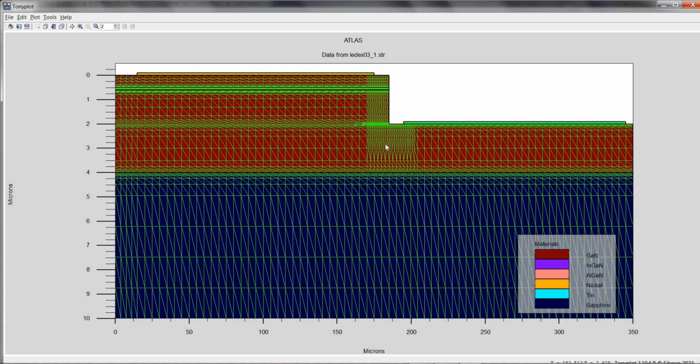At the nodes, we apply all the models that we have included in our Silvaco TCAD code: Shockley-Read-Hall recombination, Auger recombination, radiative recombination models, and a lot of other models. So if you include more nodes, the limit is 20,000, the simulation time would be longer. However, if you include fewer node points, then the results would be less accurate.